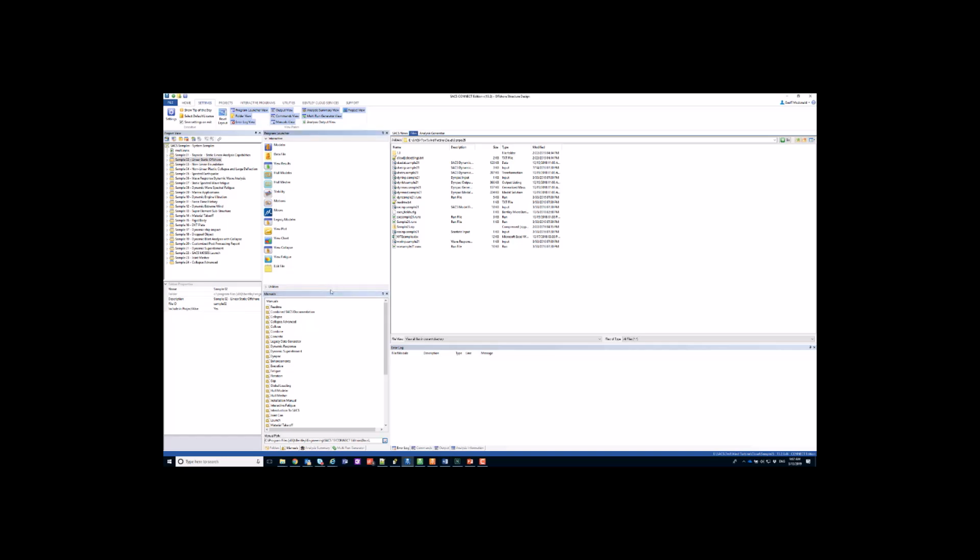So let's go to the Utilities tab. We're going to open the Utilities tab, and this is on 13 and greater. I'm on 13.2, which is a beta release right now, but you should see this in 13.1, which I think is going to be out within the next week or so. So we open this up. This is just a really simple box. It's going to get more complicated as we add more information, but you have a few different options here on which type of analysis you want to do. You can do a strength analysis, a fatigue analysis, or a dynamic superelement analysis. For this example, we're going to do dynamic superelement. It's the simplest to look at, and really once you get the concept down, it'll be easy to do the other ones.